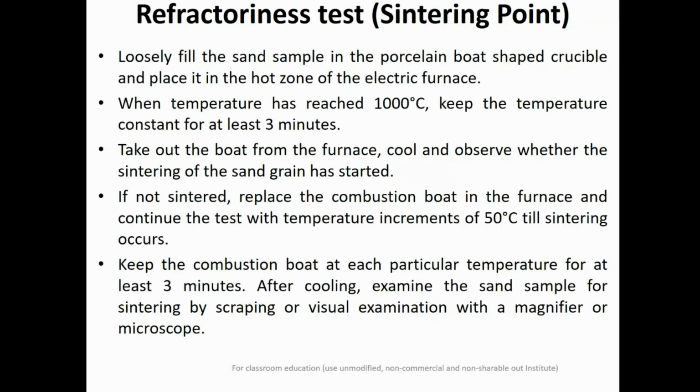So you follow the same procedure, and after 3, 4, 5 times you will have an idea of the sintering point or sintering temperature. That can easily be visualized with the help of a magnifier or a microscope. So this is the refractoriness test or sintering point test.